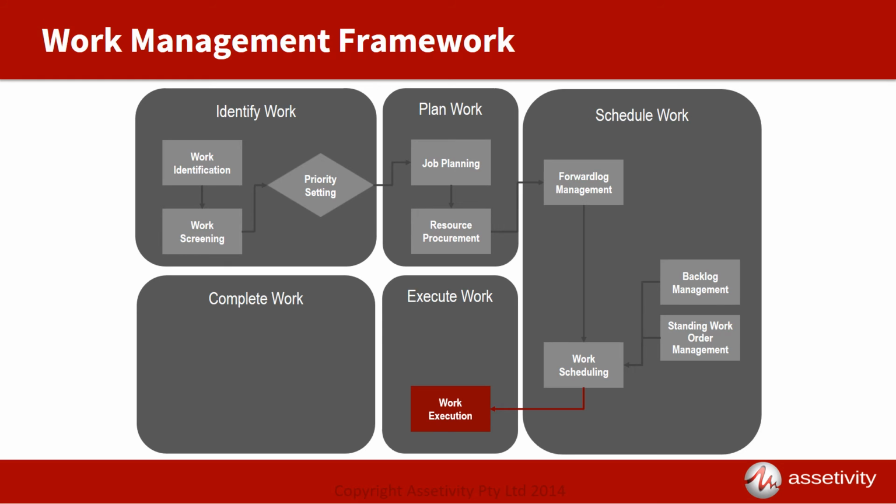In addition to ensuring the quality of the work, the supervisor needs to oversee a miniature work management cycle of their own. This is necessary to support changes to the plans and schedules arising from both breakdown work, which are high-priority corrective tasks that arise during the scheduling period, and issues such as staff illness or absences, jobs overrunning, incorrect parts delivered from store, and many more.